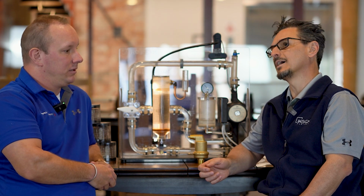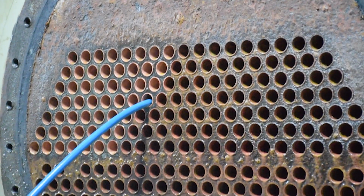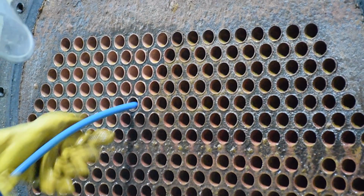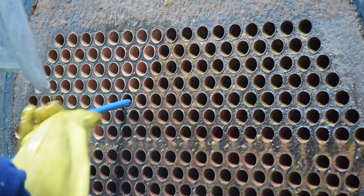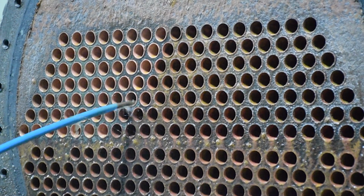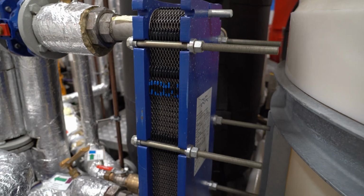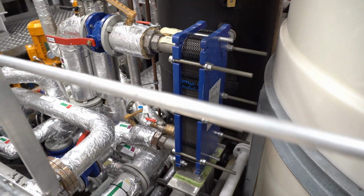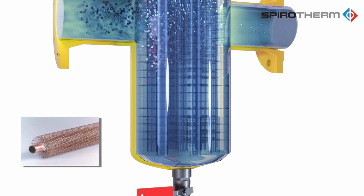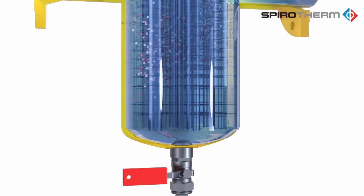Exactly. I was thinking of the centrifugal chiller days when I used to sell those. Cleaning those tubes is a major endeavor, and it's not cheap. The tubes are usually grooved inside, so there are a lot of places for the rust and dirt to get entrapped, and cleaning those is a big endeavor. It's a huge degrade in efficiency for chillers, whether centrifugal chillers or any chiller with a heat exchanger, especially a plate and frame heat exchanger. Yeah, there are a lot of tiny crevices. So maintenance, efficiency, and longevity are all super important when we're trying to keep our chill water or hot water loops clean.